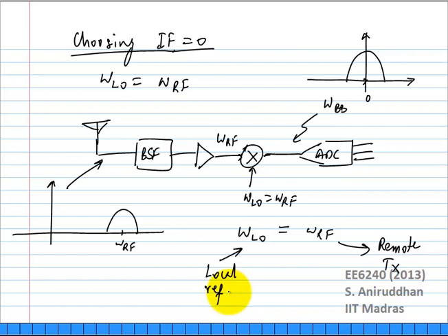Okay? But if they are very close, suppose I specify that the error in the frequency can only be so many. So, let us say the reference used, if I want to transmit exactly at 2 gigahertz, nobody can ever guarantee transmitting exactly at 2 gigahertz. There will always be an error. Right? What you can specify is the error should be, let us say, 1 part per million. Right? So if you want to do 2 gigahertz, the maximum it can be away is maybe 2 kilohertz away, not much more. Or you can say, less than that even.